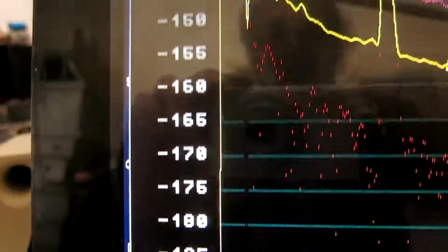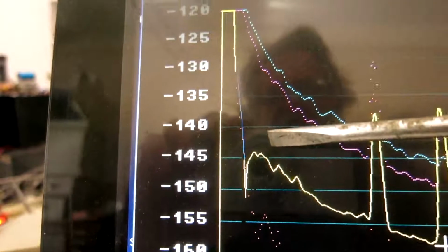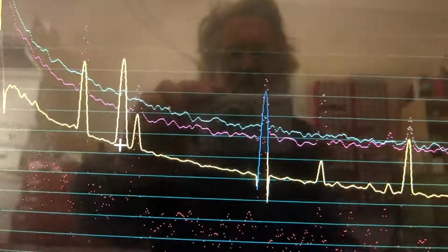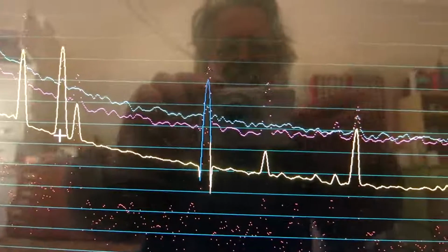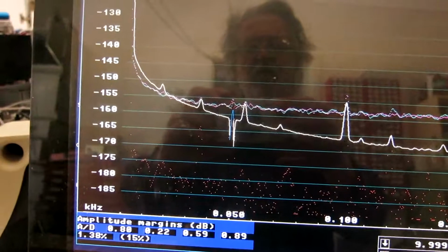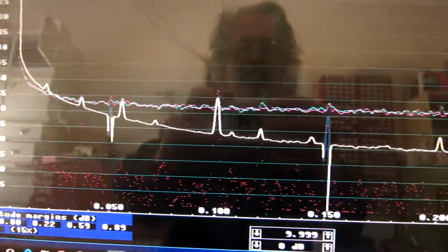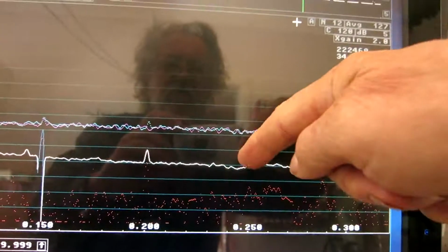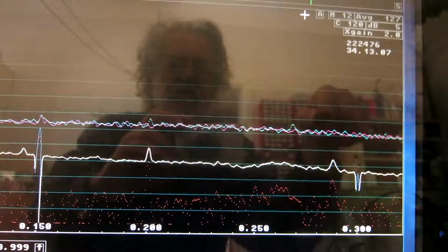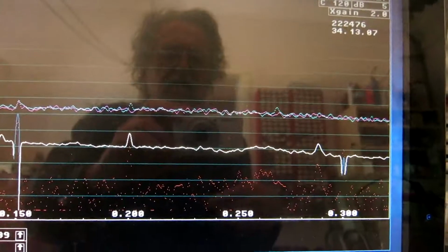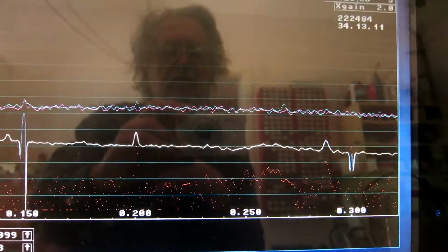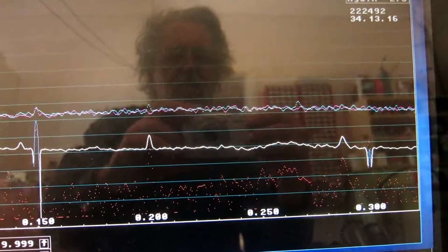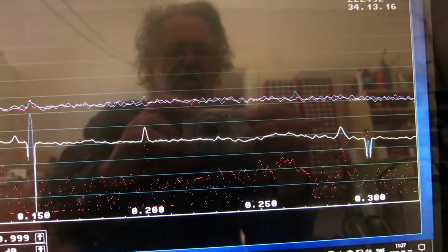That's 10 Hz here. Maybe this is still okay at 10 Hz. I will save this and evaluate from paper. And I will also save this amplitude noise. And here is obviously some kind of spur. This cannot be from the device under test, the generator from Wenzel and the filter.